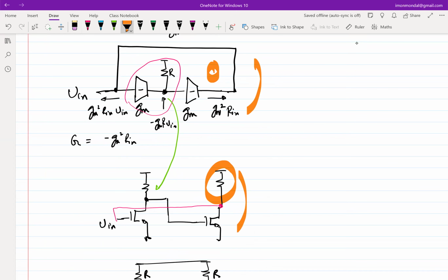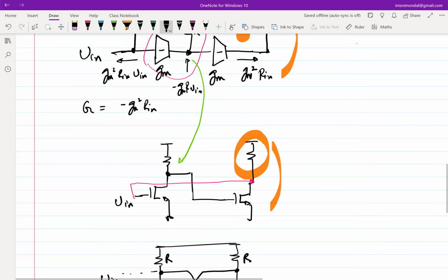That gives an additional positive part of the impedance. So when you do the calculation, some current will go into that, and effective G will reduce by the amount of current that flows into that positive resistance. So that's an adjustment you have to make. That's the only difference between the circuit on the top and the circuit on the bottom. Okay.